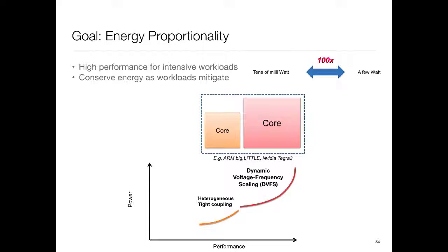So ARM, for example, has something called big.LITTLE. What happens in this architecture is processors are paired. There are two cores, one core which is optimized for lower workload, so it's this yellowish thing, and one which is optimized for higher performance, and then it's the job of some runtime mechanism to figure out which one to activate, how to activate, and whether you should use both or not.